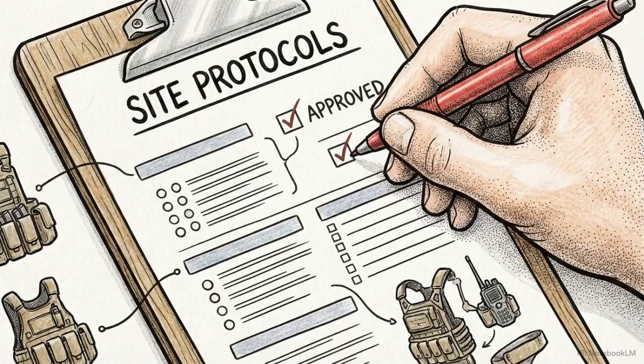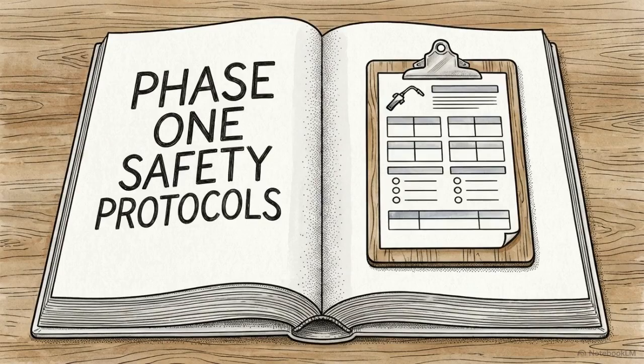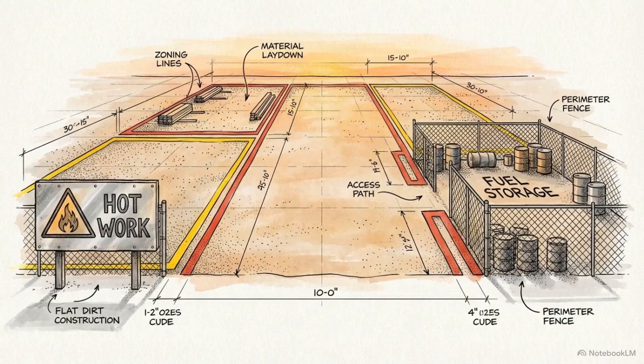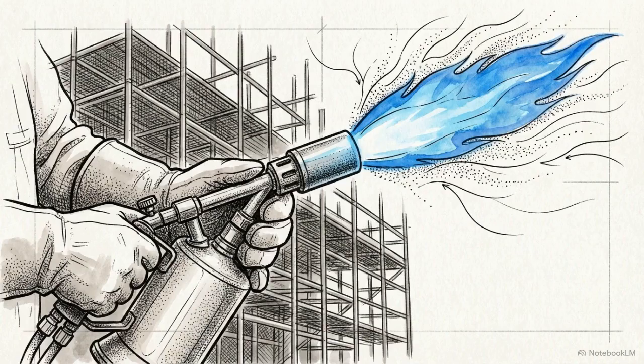These rigid requirements must be formalized within the fire safety plan, which forms a core part of the overall construction phase health and safety plan before any operational work begins. Professional site fire safety relies entirely on segregating ignition sources from fuels through strict administrative planning, long before physical walls or barriers are built. Construction introduces numerous active heat sources to a site.